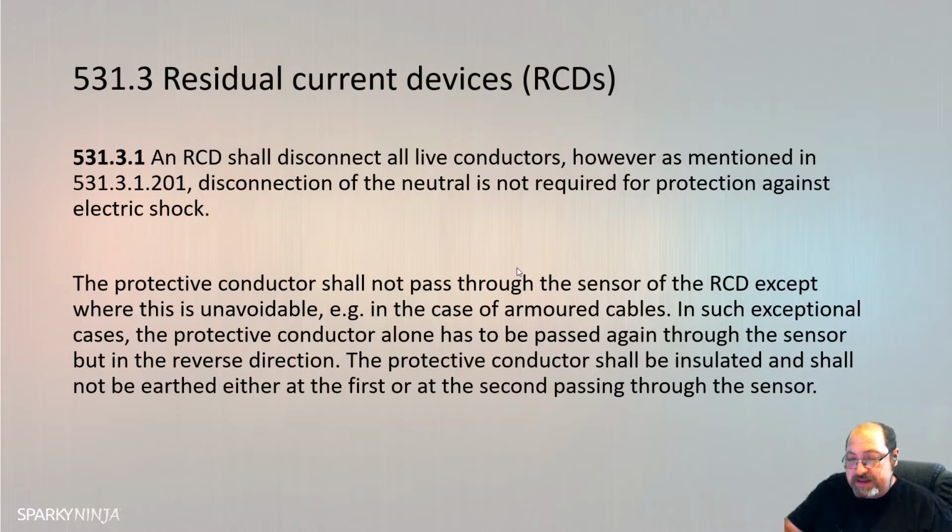We have RCDs, 531.3. Except where 531.3.1.201 applies, which is saying that for protection against electric shock, there's no requirement to turn the neutral off. You must disconnect all live conductors of the circuit.